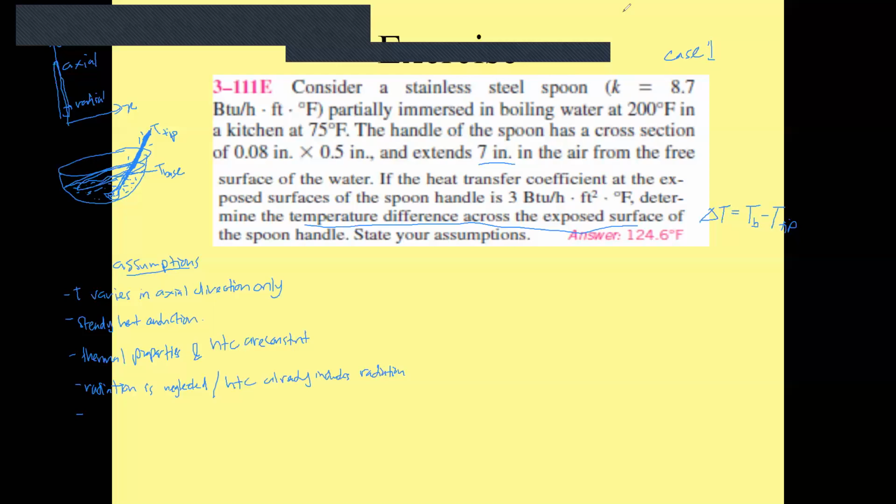this is also possible, but it didn't say that the temperature at the tip is that of the surrounding, right? Because you know that a requirement for a very long fin is that the temperature at the tip is the same as the environment, right? So yeah, probably we can keep this KIV.